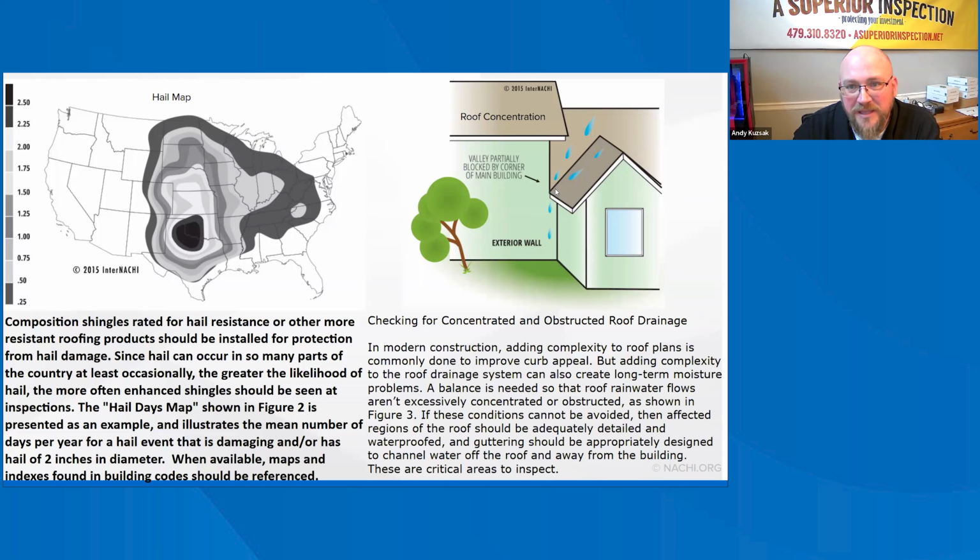If you can get to it from the attic, you should pay special close attention. In addition, and it's hard to see where these rain drips are coming down, a lot of times if this roof design is set back further, and the roof design actually came into contact with this sidewall instead of off the front here, then this sidewall intersection is also very vulnerable to water intrusion.